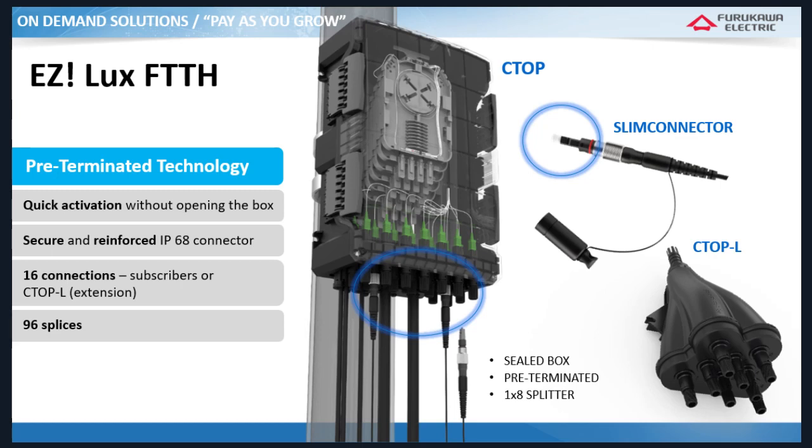So the cable comes with one end with the connector and another end that is loose, and then you install the connector in the field. Why is one end loose? Because if you need to roll out the cable through pipes, it would be impossible with a connector like that. But you are at least saving time on the closure side, because you don't even have to open it. You just connect the cable and move forward.